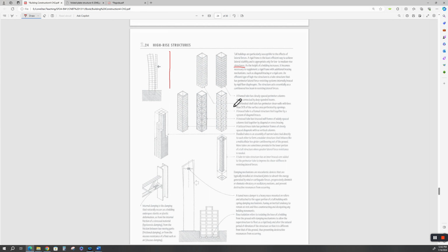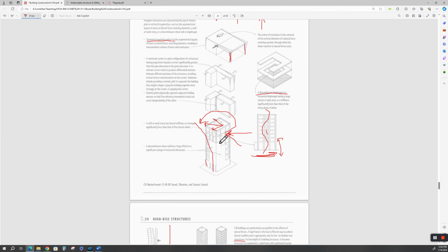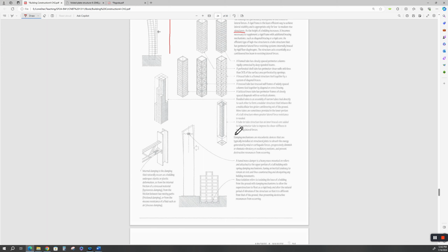Let's see. I think we've talked. Okay, that's a frame tube or bundle tube concept. What do they call this? That's the lattice truss. That would be extremely expensive to build. And we've already talked about a tube in a tube. Let's go here. This would be a tube in a tube, essentially, if you lattice truss some of this and your structural stuff all tied to it. So you've got a center core, and essentially, now it doesn't float apart like a gust did, but that's really what you're trying to do.